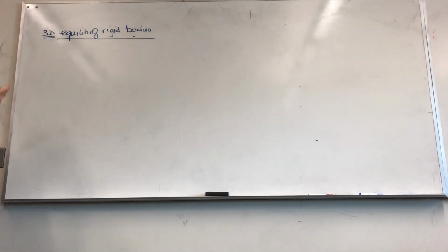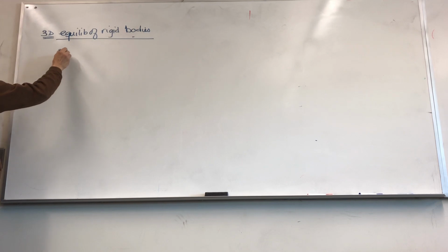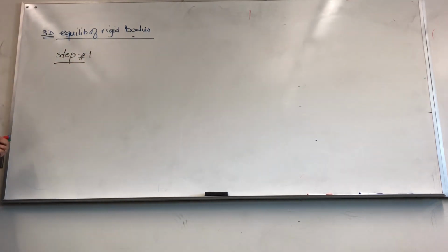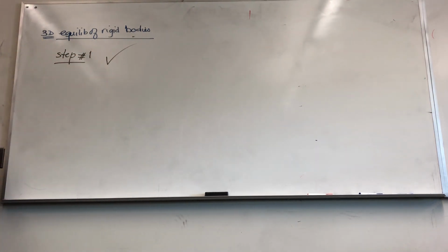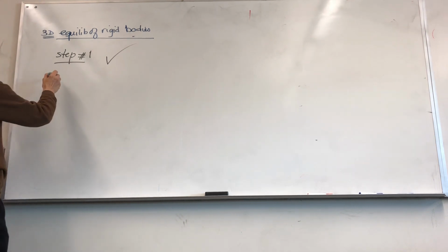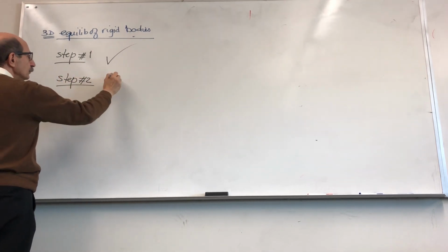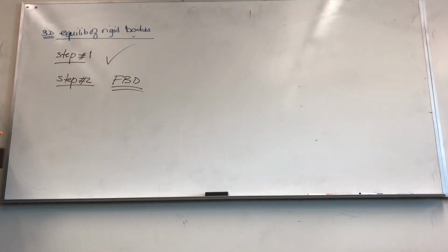And so with that said, the only thing that really is different is that, first of all, step 1, which is setting up the coordinate system, is always given. Usually when you're given a 3D structure, coordinate systems are set up. Step 2 is the same. You still have to set up the free body diagram with the understanding of what functions each support system represents.